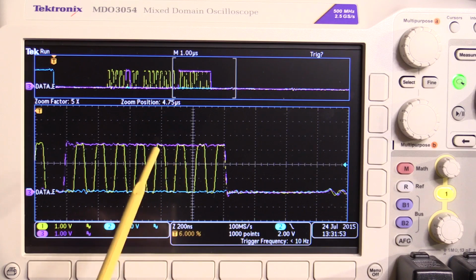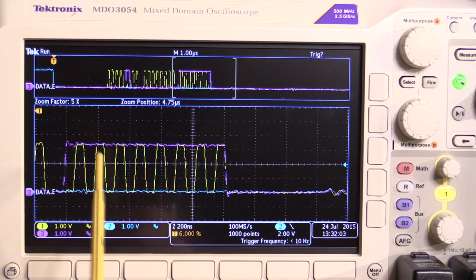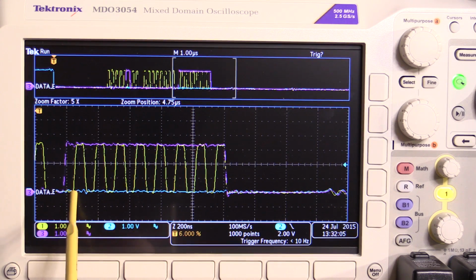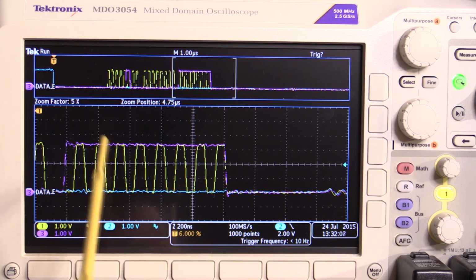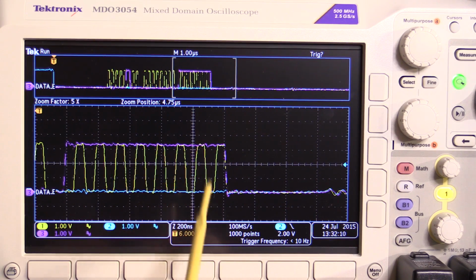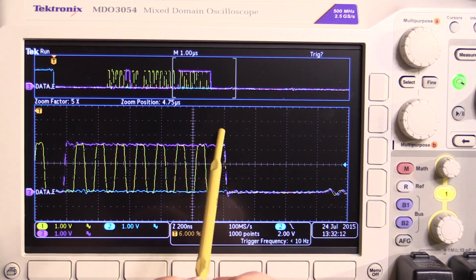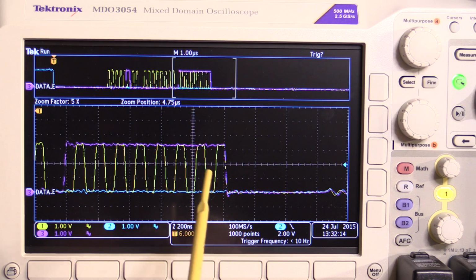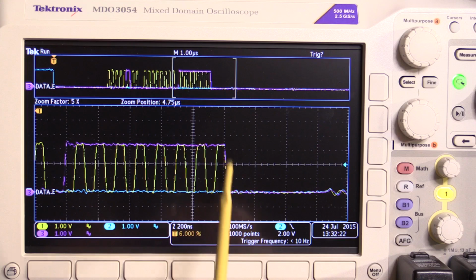And so even though my controller, which is the Raspberry Pi, is now working in mode 0, of course my device, which is the DAC8734, still wants to work in mode 1. So the Raspberry Pi is outputting a 1 on the positive edges of each of these, and there's 8 of them, of course. But on the negative edge, the DAC8734 is going to be clocking its data in. Even though the Raspberry Pi is clocking the data out on the positive, it's clocking in on the negative.